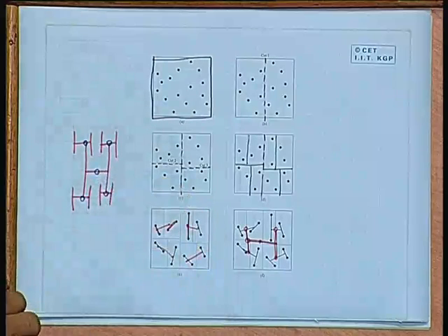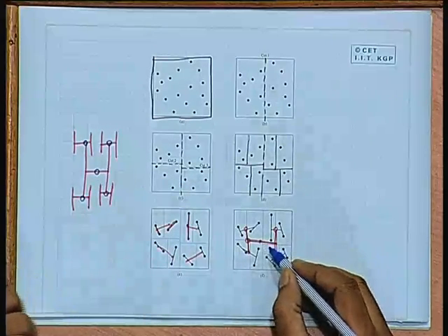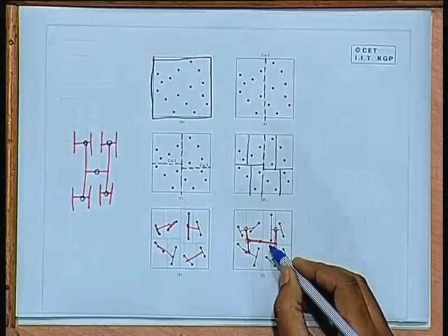We are using a separate layer for this clock routing. So on that layer itself we are not putting the buffers. Buffers can be laid out on a single layer if layouts of buffers are available. That is one thing I did not mention. I mean the interconnection, that means the input and output. But they will have to go through the polysilicon diffusion layer because they are active components.